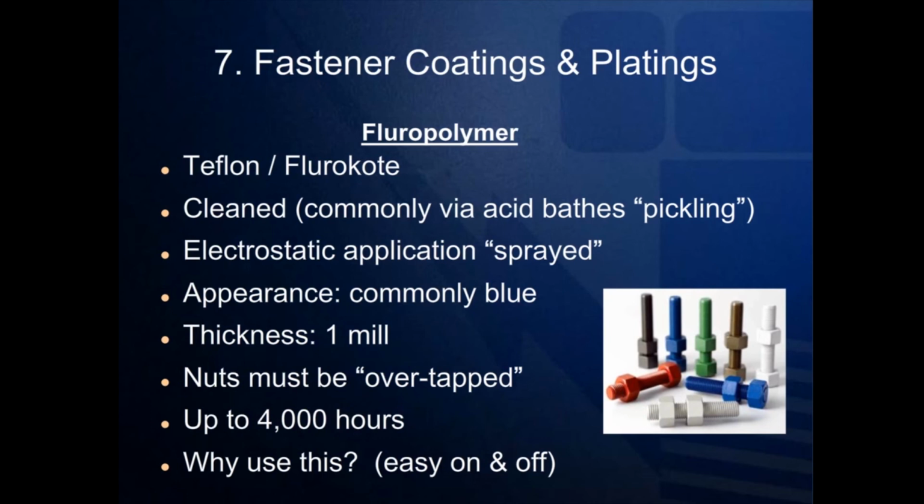For example, the Teflon-based coating provides very superior protection against corrosion. Therefore, years can go by and the nuts can still be disassembled from the studs. This would be important in petrochemical plants that would need to change out a valve or pipe handling gasoline. No one would want to risk an explosion for lighting a cutting torch to cut apart the rusted out bolt and nut. It is common to have Teflon-coated commodities that are stocked for offshore and petroleum applications to include B7 studs and their corresponding 2H nuts, F436 washers, and B7 heavy hex cap screws.